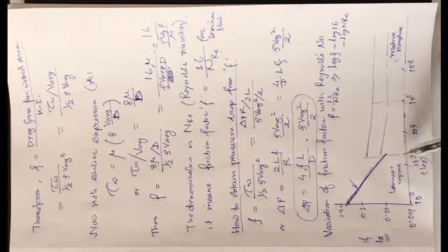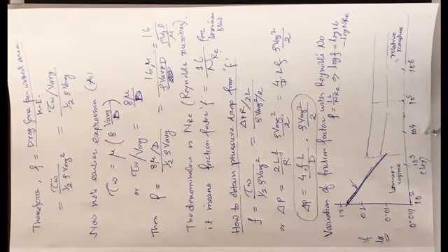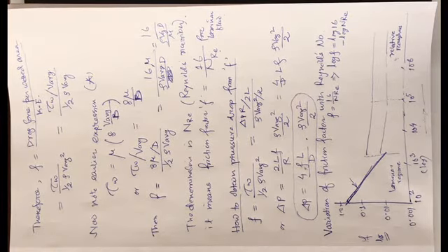Up to here, we have seen what happens in the case of laminar flow. Mathematically as well, the value of F is inversely related to the Reynolds number. As Reynolds number increases, the value of friction factor decreases. So that's all. Even our textbook gives this information, the chart is given, so you are advised to refer to that.